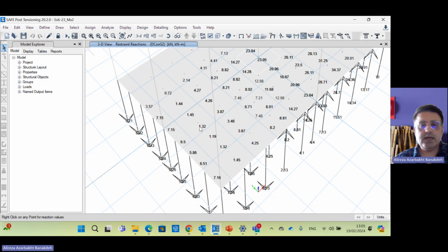It is not in agreement with reality, because in reality, when the foundation uplifts, there is not anything between the foundation and the soil. So it can uplift, but there should not be any force between the surface of the foundation and the underneath soil. That's the reason we need to somehow simulate this in our model, which obviously is not working like this.